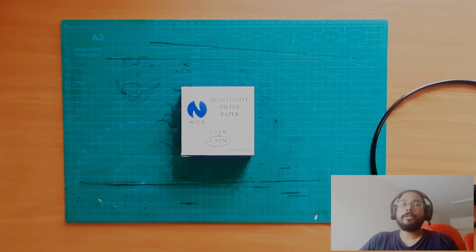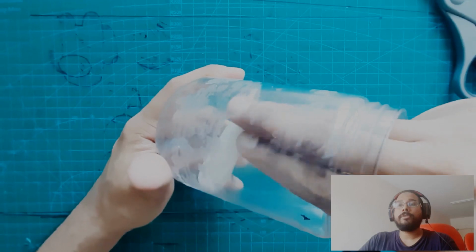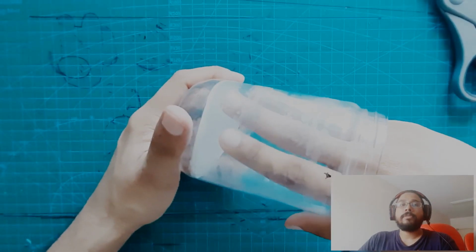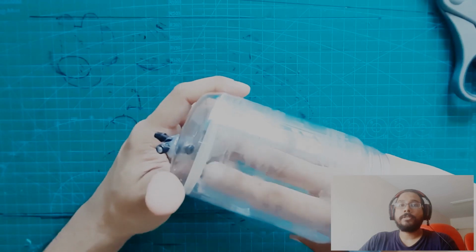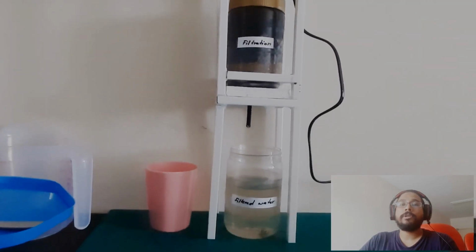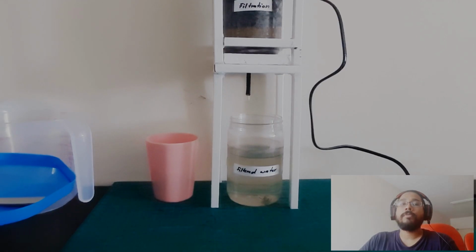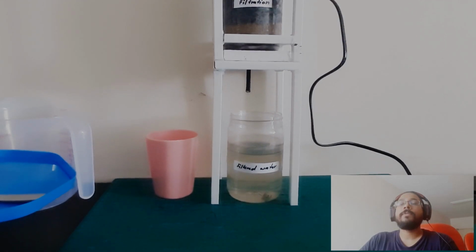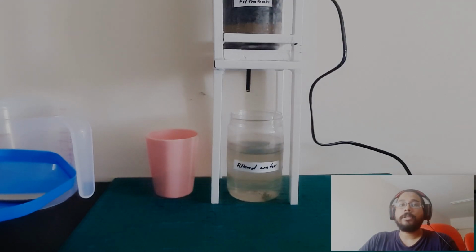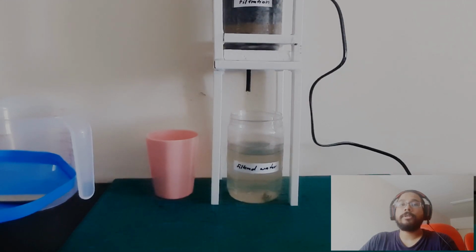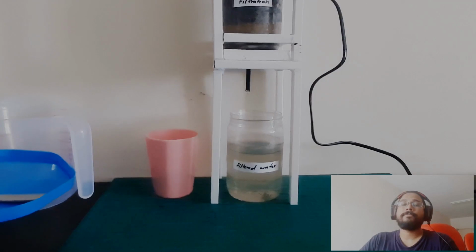The last factor that could have affected the results is the filter paper size. The filter paper used was not sufficient to remove the very fine particles in this experiment. The size used in the experiment was 10 to 12 micrometer. The pore size was enough to remove the bigger particles in the water, which was able to give the treated water a clearer appearance visually. However, it was unable to remove the very fine particles that contributed to the increased turbidity and EC values. A correction for this would be to use even finer filter paper with smaller pore size.